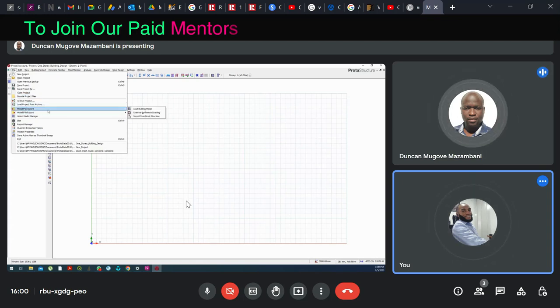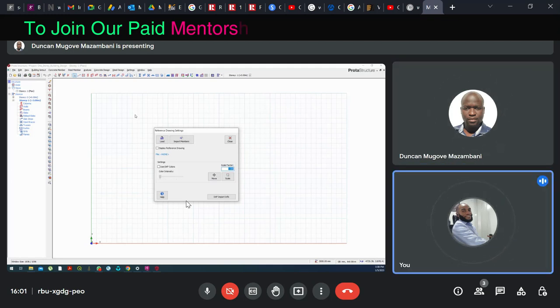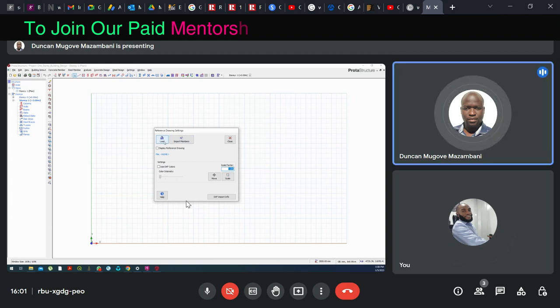Then go to Model, File, Import, External Reference Drawing. Then click on Yes. Select DXF, and then locate the file where it is. DXF load.